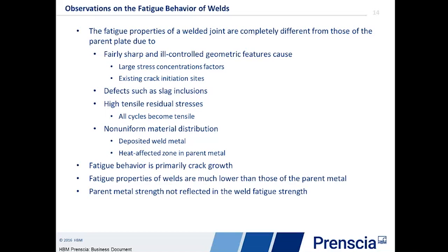Again, the fatigue properties of the welds tend to be much lower than the fatigue properties of the parent metal that was welded. And then finally, if we look at the behavior of welds across a wide range of alloys, the fatigue behavior of those welds is very similar.